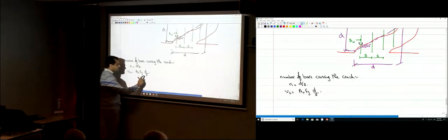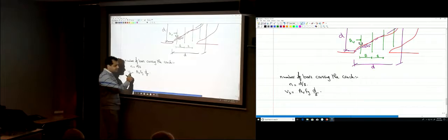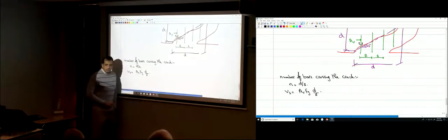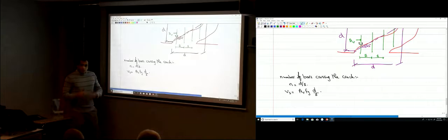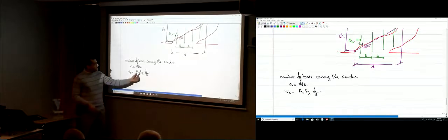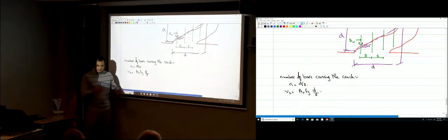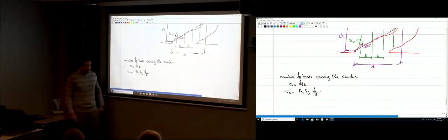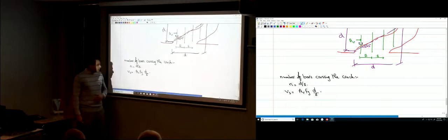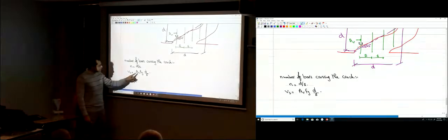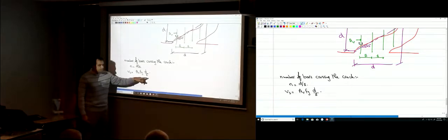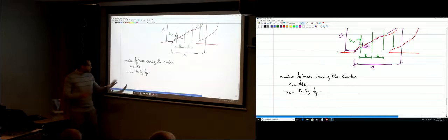So what are the things that you can play with to increase the shear strength that is provided by the steel? It's Av and S. To provide more strength, you can increase the area of the stirrups, or you can decrease the spacing between the stirrups. You can have smaller S, or you can have more Av. So based on how much Vs you need, you're just going to find a combination of Av and S to reach the Vs that you need, okay?